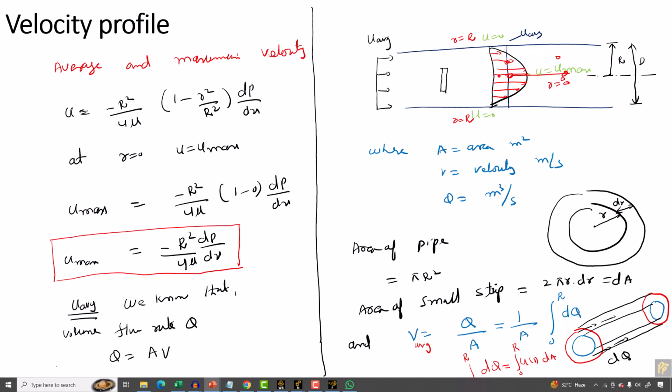So once the flow is fully developed, we should be getting the maximum velocity at the center. And because we know the formula that U maximum is twice the U average, or U mean, or the velocity we provided on the inlet, if I display the velocity on the center, it should be equal to 2 times U average, which is 1. So it should be 2 meters per second.